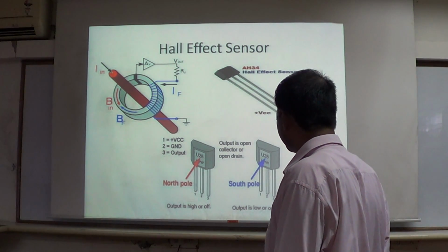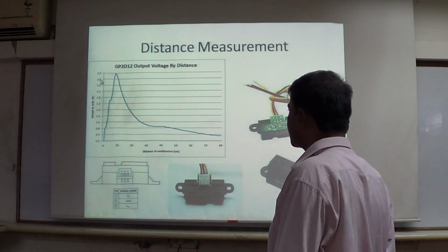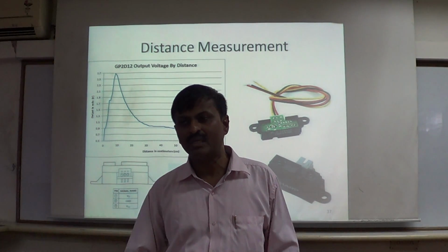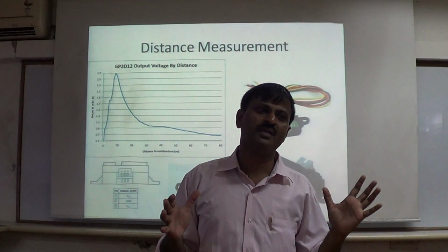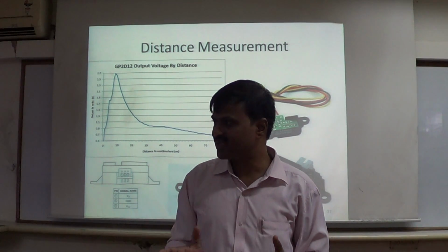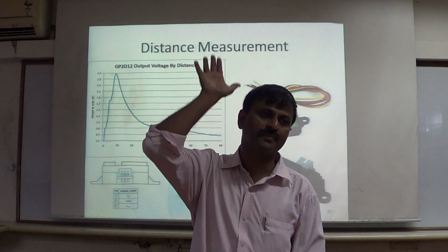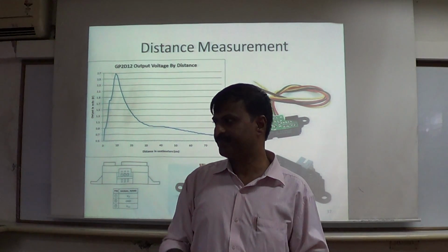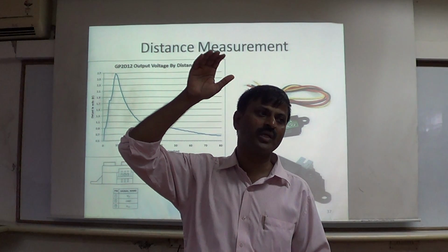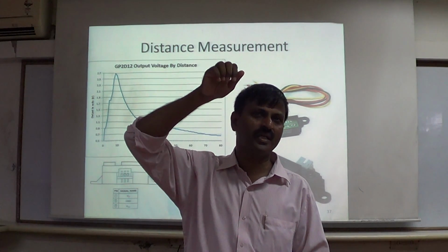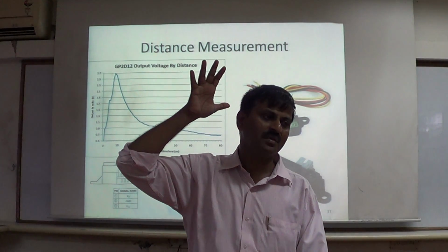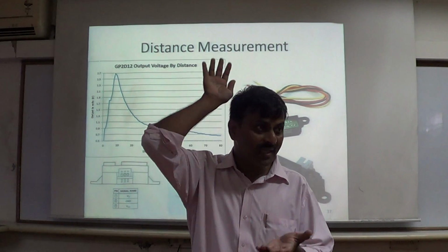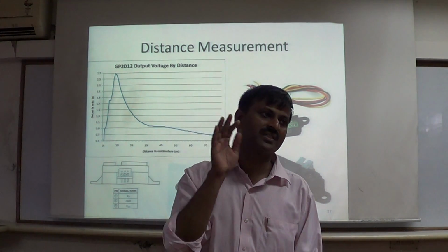These are also popularly used, and there are also other types. Distance measurement, sometimes I will show you in the afternoon, we need to measure the distance also. For example, with that solar dish, daily tracking happens east-west, but seasonal tracking happens north-south. This tracking is 46 degrees. So for this 2-ton dish, you will have to either compress it or expand it by 46 degrees. This is called seasonal tracking. That means the sun's displacement in a year, north-south, is 46 degrees.